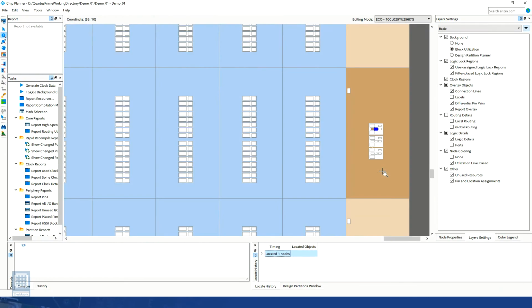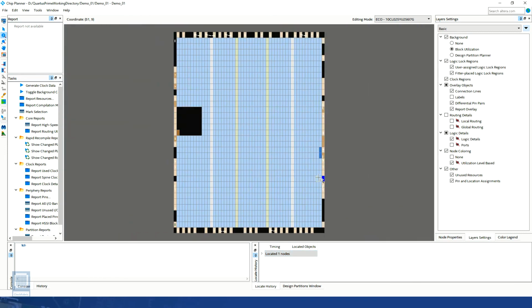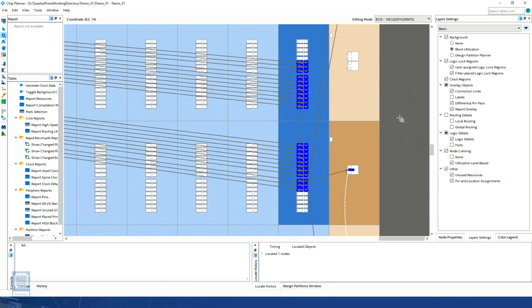locate in chip planner. In the chip planner, we can see where in the FPGA die our node is located. It also shows all the logic elements being used by our design. If we select the zoom tool from the toolbar located at the right of the screen and right-click several times, we can have a bird's eye view of the FPGA device. Now if we select the selection tool that looks like a mouse cursor and select the whole FPGA device like this and click on the expand connections icon, then we'll be able to visualize actual connections between the nodes being used by our design elements.